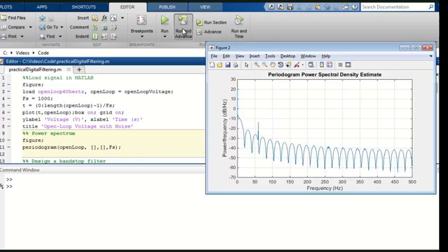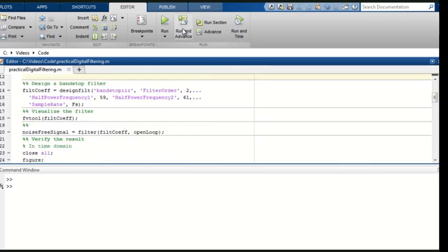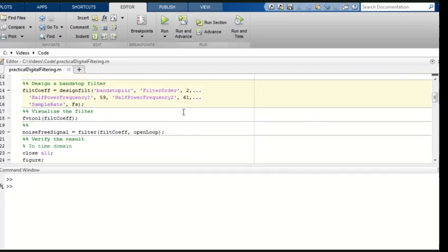You can see a peak around 60 Hz in the plot. This peak is likely caused by the presence of 60 Hz power line interference, which corrupts electrical signal measurements. We can use a bandstop filter to remove the 60 Hz interference. A bandstop filter with a narrow stop band eliminates a tone of a particular frequency.